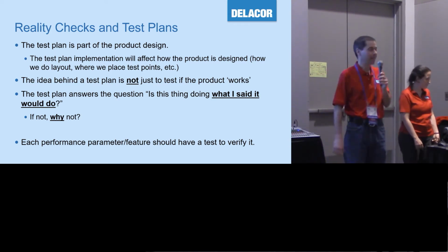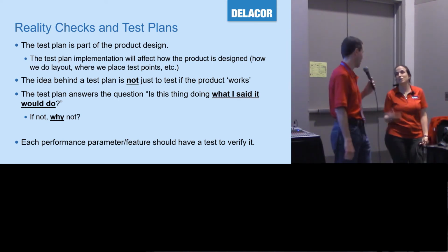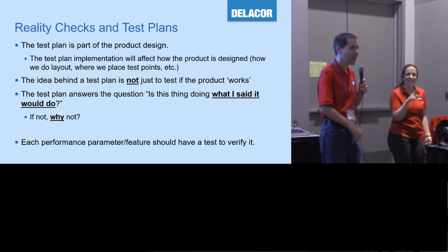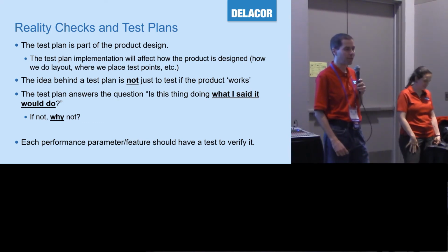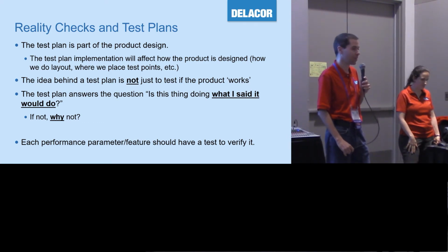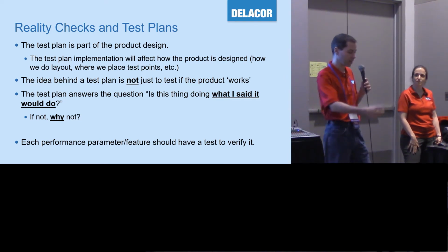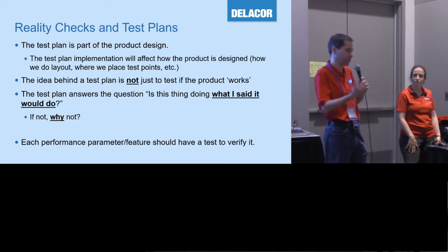Well, it depends. I could talk for the whole day about just that question, but it depends what you expect the ADC to do. If you're testing linearity on an ADC, you are going to hook it up to some very, very linear source, and then you're going to read with a computer or some sort of digital device.